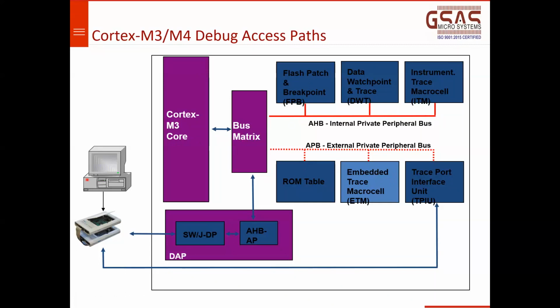So it's up to the silicon vendor to decide whether these blocks have to be included. And if at all the blocks are there and you want to use them in your application, then this AHB to APB bridge has to be programmed.